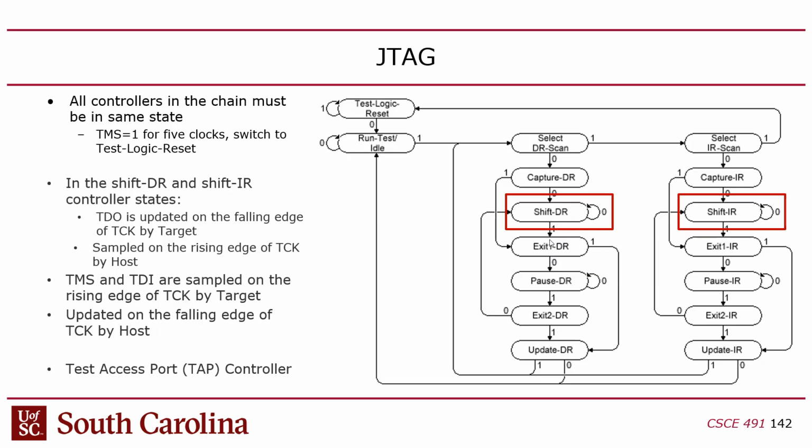So that way, whenever you start a JTAG, I don't know if you guys remember this from 3.13 and 6.11, but when you open up your JTAG viewer, it'll automatically detect what chips are on the chain. And I always wondered how it did that. Well, the way it does that is it reads the ID register from each chip in the chain. And so you can plug in a bunch of chips on your JTAG chain and then it'll self-identify them by reading their IDs.